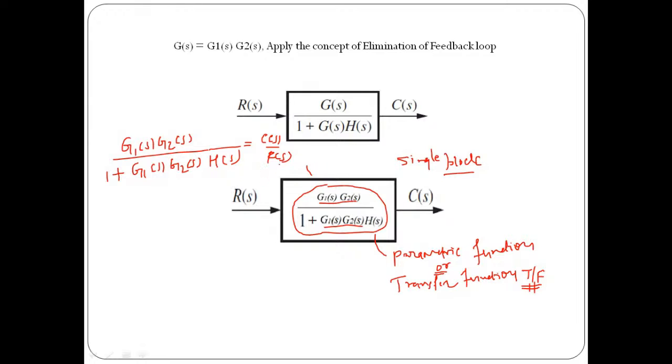So this is a simple numerical through which we can understand what exactly the block diagram reduction technique is and how we can apply those simple rules to find out the transfer function through BDRT rules. That is important. And this type of numericals were asked in GATE. The complexity of the numericals is quite tedious, but ultimately you need to apply some set of block diagram reduction rules to convert that system into its equivalent single block, and whatever function we get inside that block represents the transfer function of that system. That is important.